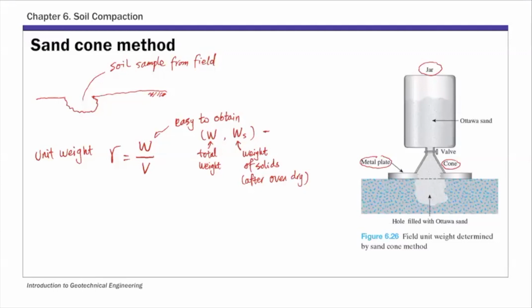So you can calculate small w, this is moisture content. That's very, very easy. So everybody can do this. You can take a soil sample, weigh it, dry it, and weigh again. So we get all these quantities.